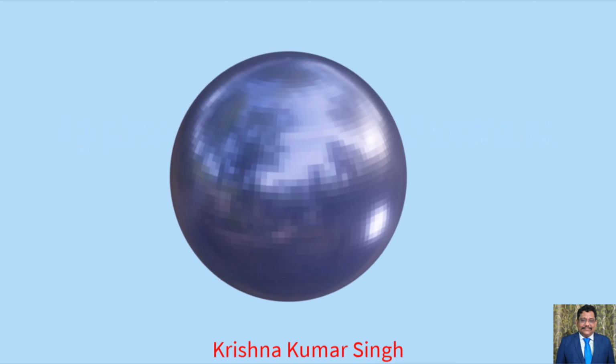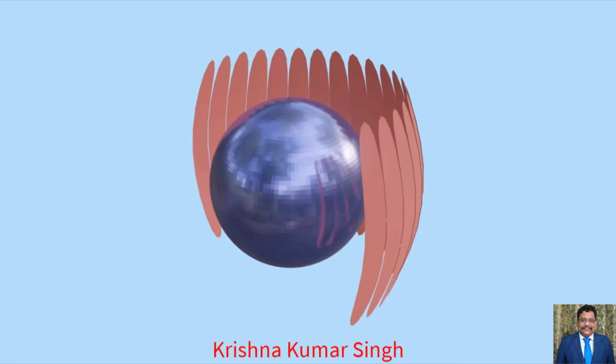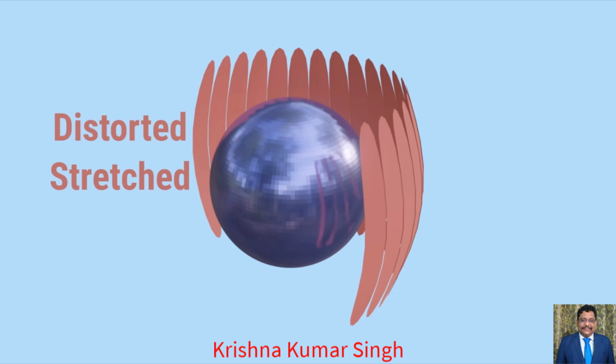It is employed for double curved surfaces like spheres. As developing a sphere on a 2D plane is not possible, for developing a sphere, the approximate method of development is used. So basically we have studied that the approximation development pattern is distorted or stretched to obtain its final shape.